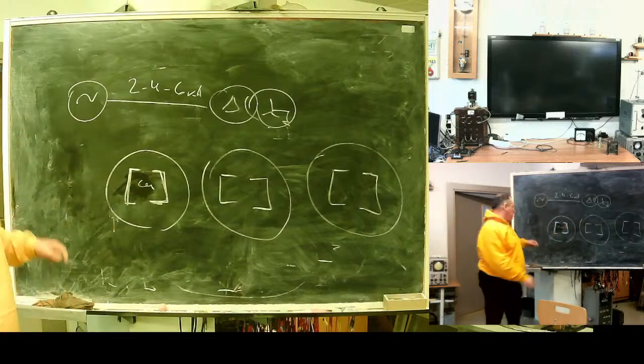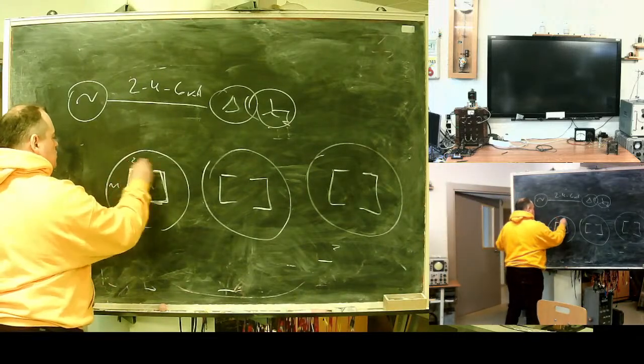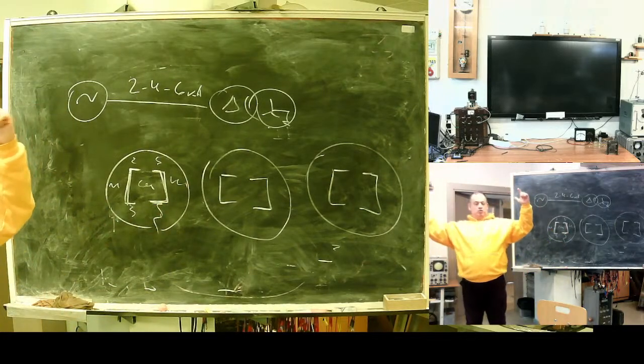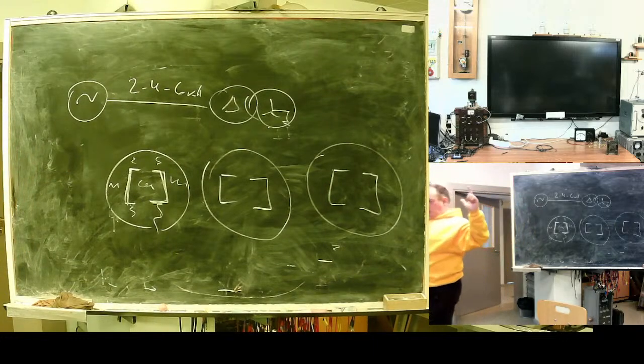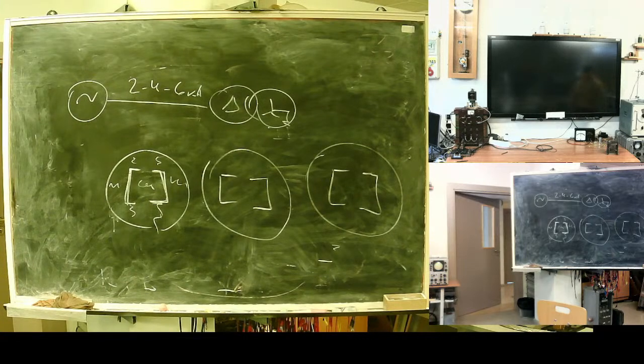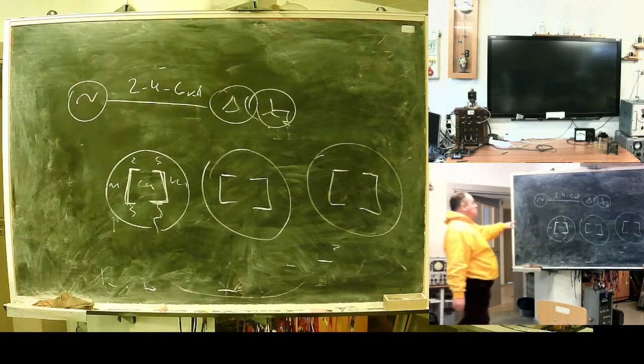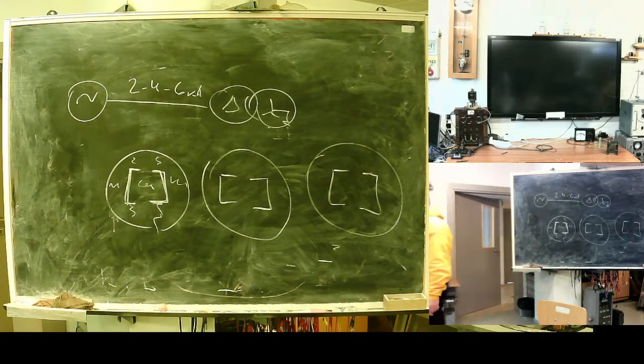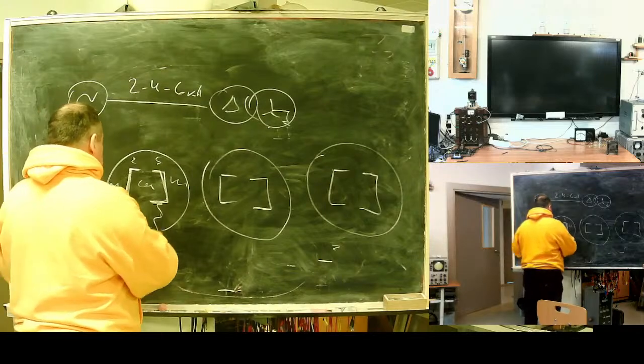Inside copper buses. Insulators. Like this. Outer diameter more than a meter. Like this. Problem. How to plan earthfault protection. Problem with earthfault protection for generator. You cannot put a cable transformer there. It's really 3 pipes like this. One of the solutions is a special cable bus transformer.